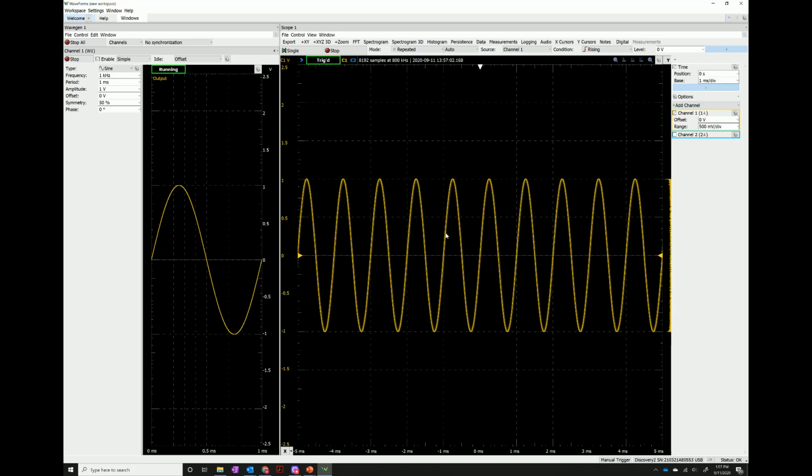Note that that transmitted signal here has a 1 volt amplitude. Right? We've specified 1 volt here. We can see this as -1 to 1, showing our 1 volt amplitude. And we also see this on our scope's range. Right? So the signal that's received on our scope, because we've directly connected this, has an amplitude of 1 volt as well. Right? Showing up here with our axes labels on the left.